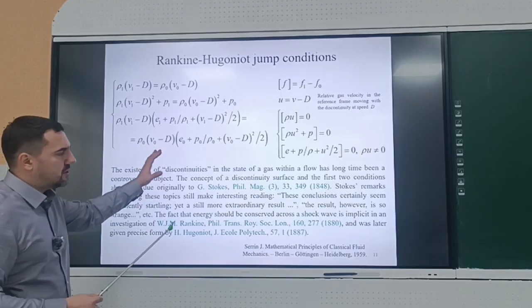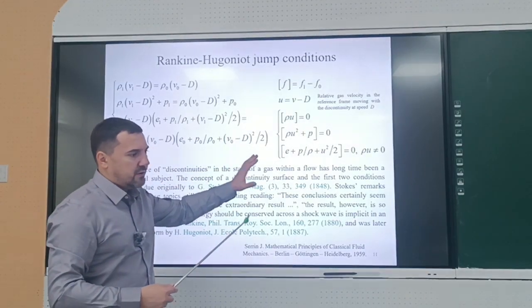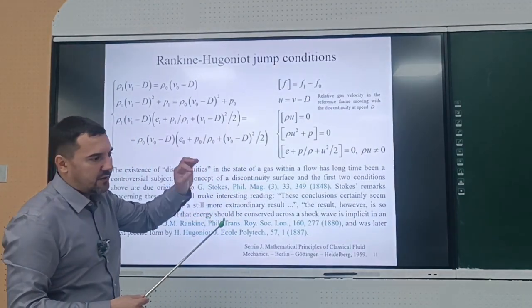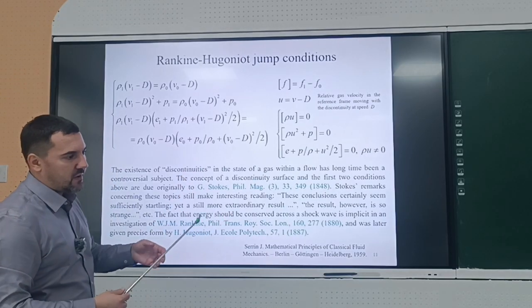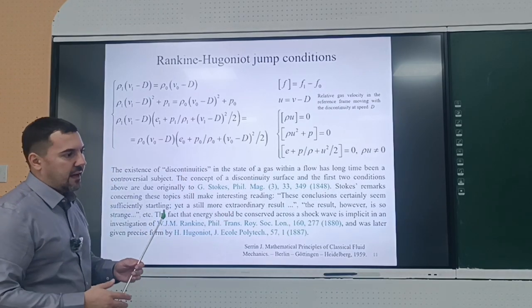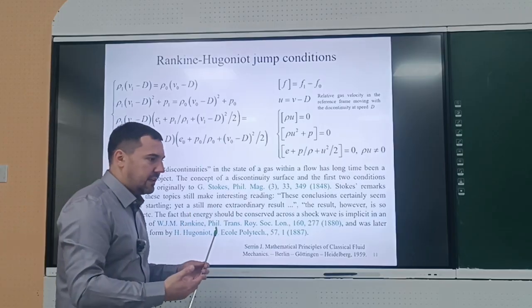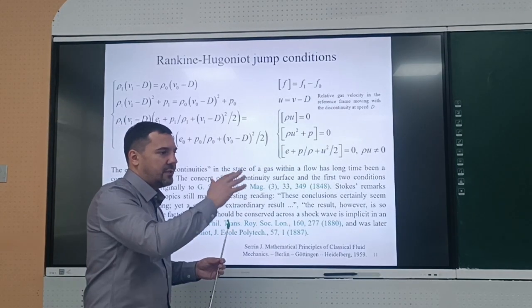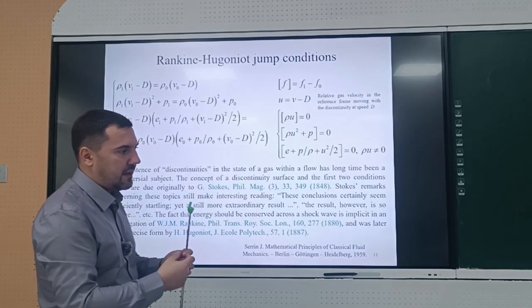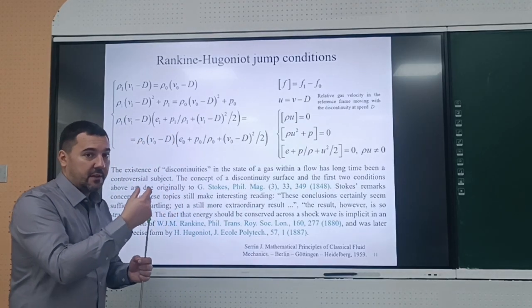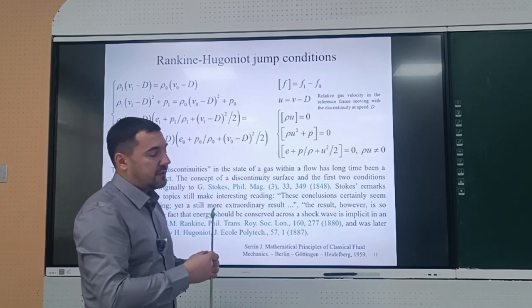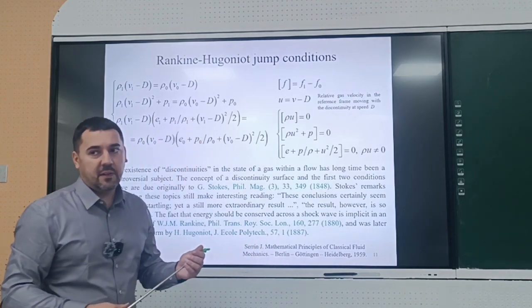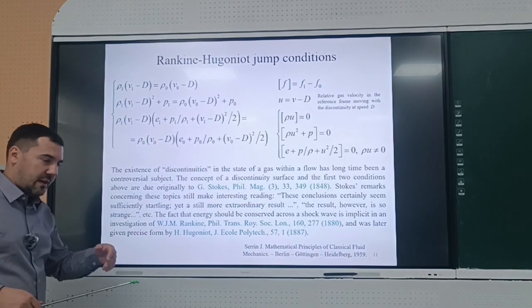The thing is that, for sure, in reality you don't have an infinitely thin structure. In reality, you have viscosity, and in viscous media the shock wave is a structure with very sharp change of parameters, but nevertheless of some certain thickness. The thickness of the shock wave is about the order of magnitude of 3 mean free paths of molecules.